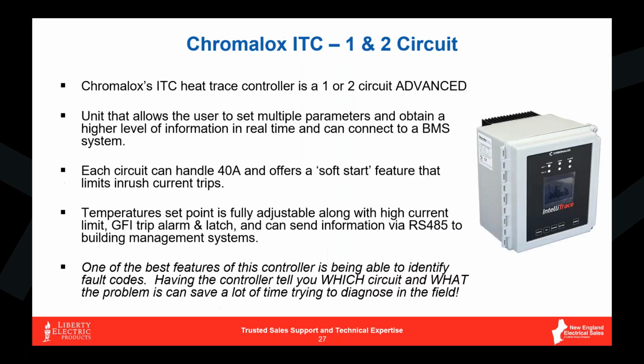So speaking of that, here's our integrated Chromalox ITC. This particular electronic controller has a 1 or 2 circuit option when we send these out to the field. Basically, long and short of it, the master board is the bottom board. If you open up that control panel cabinet, you're going to see 2 circuit boards on the right half of the equipment. The lower board is your master board. The upper board is the slave circuit board.